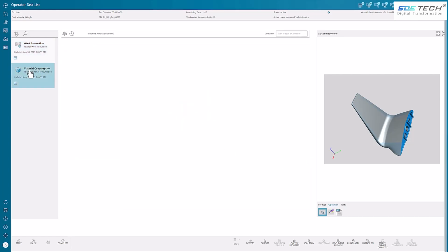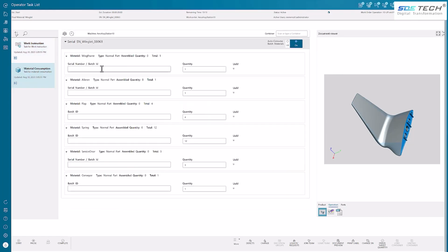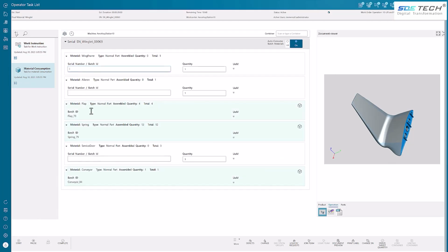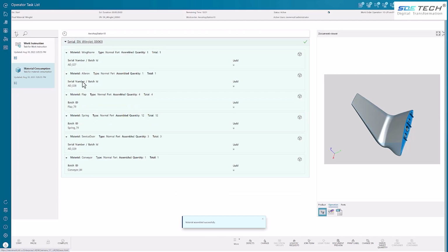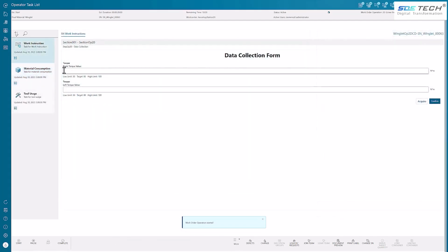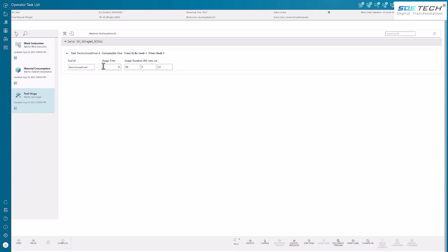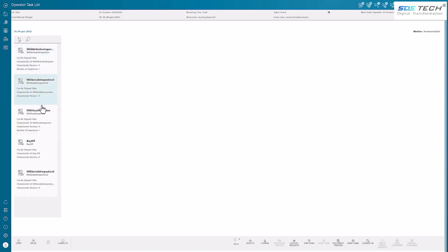Material validation is done at the point of consumption, with the ability for Opcenter to allocate line-side materials, and I can scan and validate serialized components. With connectivity to smart tooling, Opcenter can acquire data from my shop floor operations and automate the data collection, such as torque measurements. Tooling data such as usage count and time is obtained and recorded from the connection to give me a better understanding of my equipment's health.